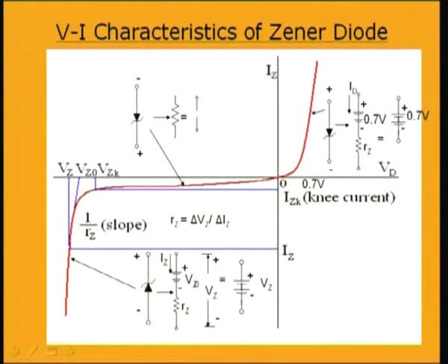So, ultimately we have this model of the Zener diode in the reverse breakdown condition as having the voltage VZ, which is equal to VZ naught. So, this part can be neglected. What we get across this Zener diode after Zener breakdown has occurred is that a constant voltage drop VZ is maintained, even though current can change. This particular phenomenon is very effectively utilized, as we will see later. So, once this reverse breakdown occurs, the voltage across the Zener diode will be locked at the voltage VZ.